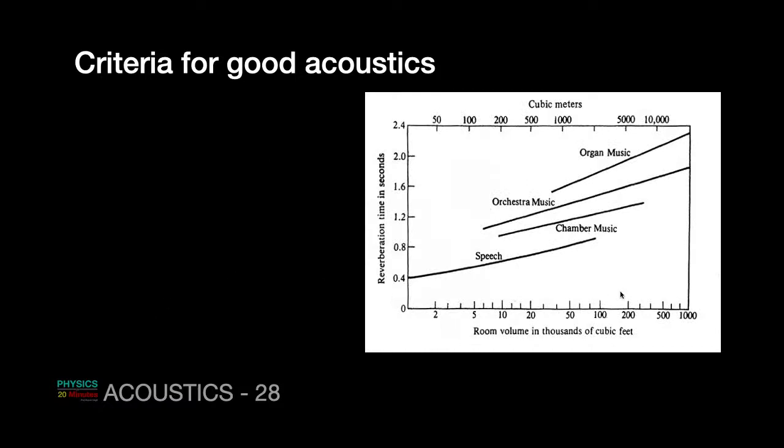Here are practical observations of what kind of reverberation time is needed for what kind of oral activities. You can see that speech can go up to around 0.8 second. But music typically starts at around 1 second and can then go up to a higher value, 1.2 seconds or 1.6 seconds, depending on what kind of music you are listening to.